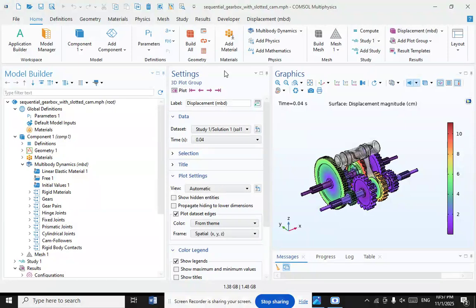counter output shaft. And what about the dog clutch? In a modern constant mesh manual transmission, the gear teeth are permanently in contact with each other and dog clutches, sometimes called dog teeth, are used to select the gear ratio for the transmission. When the dog clutches for all gears are disengaged, for example, when the transmission is in neutral, all of the gears are able to spin freely around the output shaft.